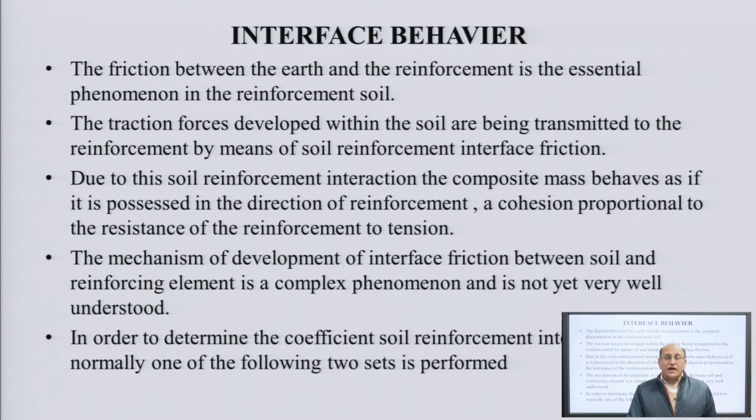Now we come to the interface behavior of the soil. The friction between earth and the reinforcement is an essential phenomenon in reinforced soil. The traction forces developed within the soil are transmitted to the reinforcement by means of soil reinforcement interface friction.